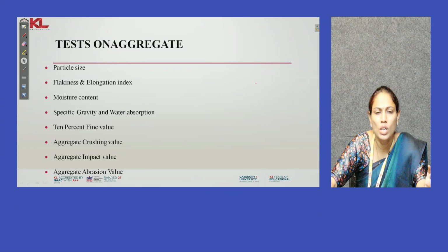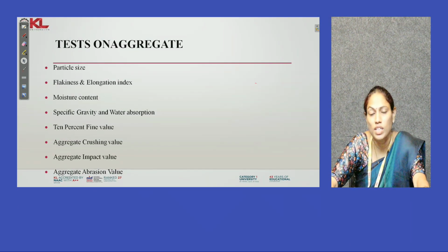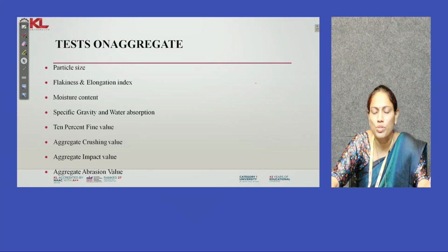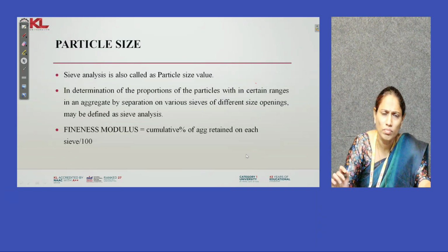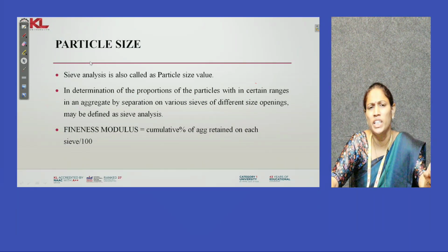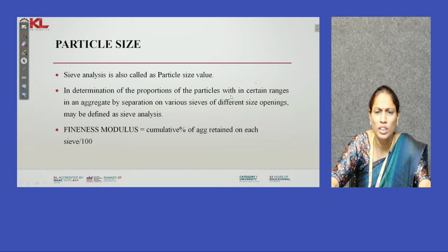Impact value means when a sudden load is given on the aggregate, we see what the condition of the aggregate is. We are also going to check the abrasion value in the Los Angeles test, where we keep some steel balls and see the wear and tear of the aggregate. Particle size, sieve analysis, is called the particle size value. Determining the proportions of particles within certain ranges in an aggregate by separation on various sieves with different size openings is defined as sieve analysis.